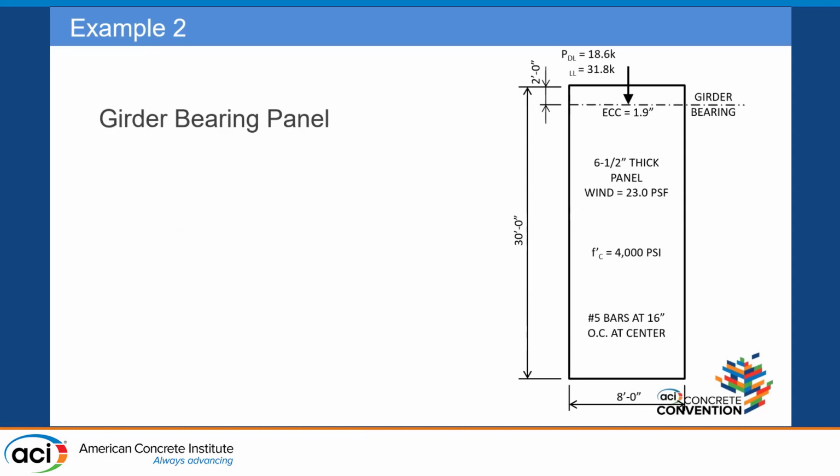But the challenge is that you're now designing on this elastic part of the curve. What happens when your panel suddenly cracks? Whether it's an overstrength event, whether it's during lifting, maybe the panel has some impact. If you're designing down here on this vertical part of the curve and the panel gets cracked, you're not going to have the steel necessarily to arrest this panel from getting excessive deflections and sort of crushing. Fortunately, the test results are that these panels do behave pretty ductilely, and they can take a lot of deflection. But our equations are clearly saying this is an area of design you don't want to be in. So one more example, we'll go through quickly here.